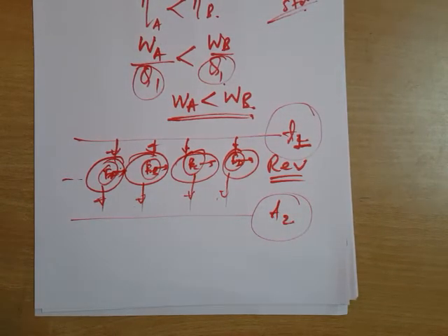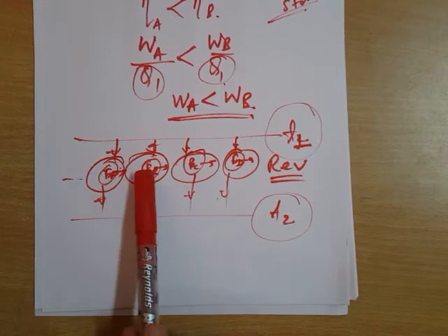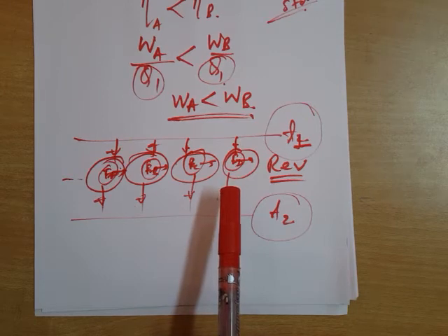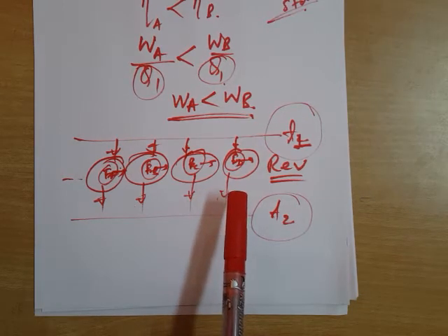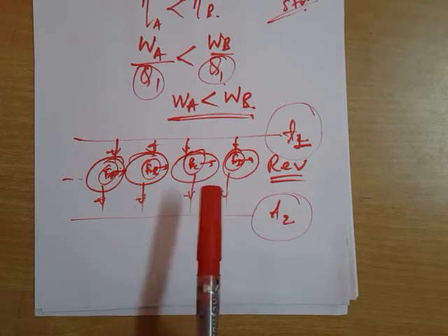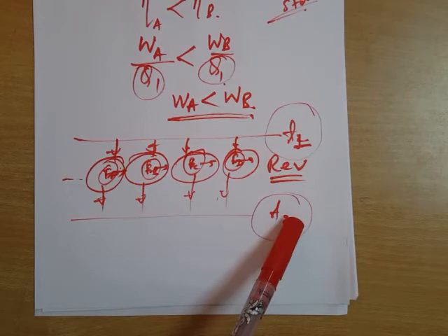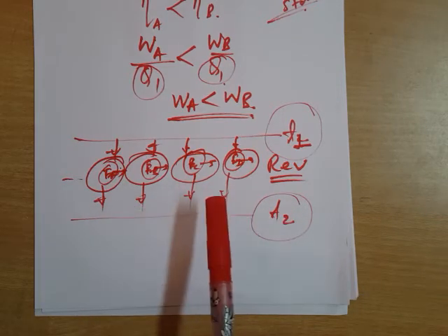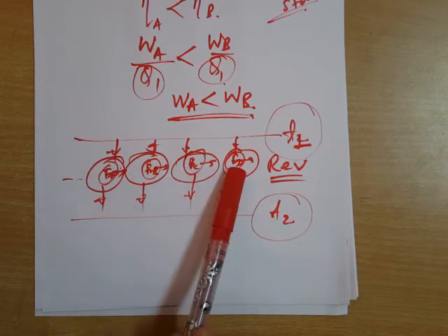So this simply means, in a general sense, that these are all different engines, and their working fluids will also be different, yet their efficiency is the same. That means if reversible engines are working between the same temperature limits, then efficiency becomes independent of the nature or amount of working substance used in this cycle.